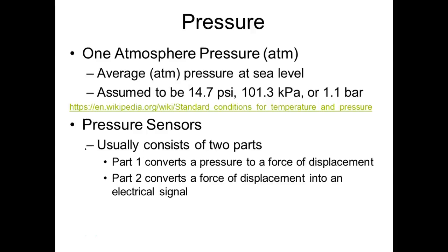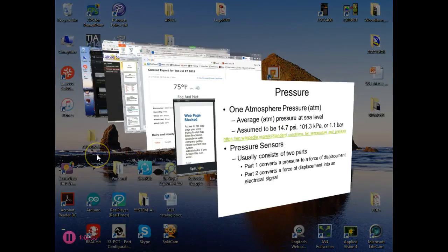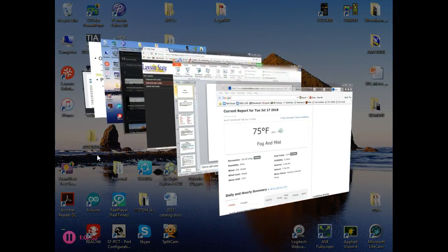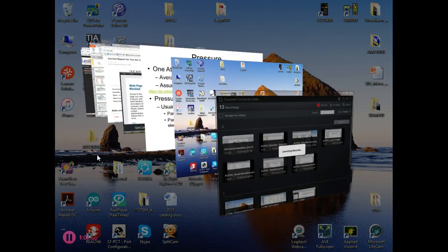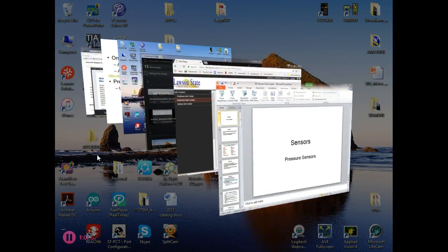This range is fixed, so you can't vary it. That's true on most home compressors. Most home compressors run between 100 and 170 psi, but just about all the tools that you have access to are rated at 60 psi. This is the actual compressor right here, and it's a reciprocating compressor, which is a pretty standard compressor.